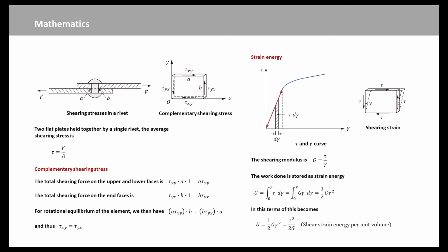In shearing the rectangular prism, the forces acting on the upper and lower faces undergo displacements. Therefore, work is done during these displacements. If the strains are kept within the elastic limit, the work done is recoverable and is stored in the form of strain energy. Suppose all edges of the prism are of unit length, then the prism has unit volume, and the shear forces on the shear faces are tau.